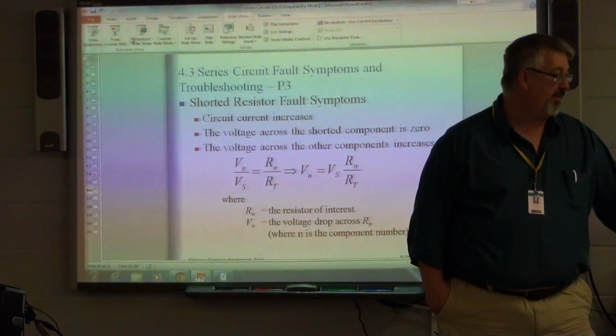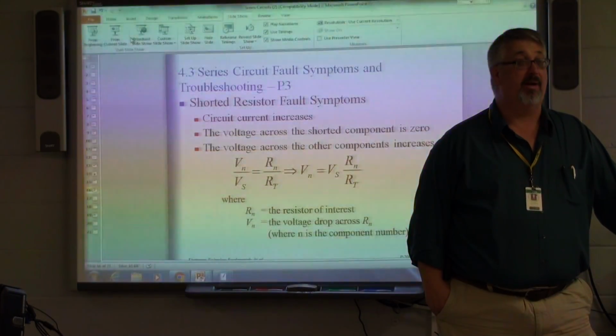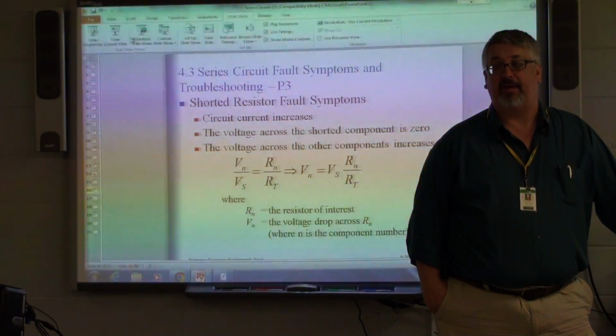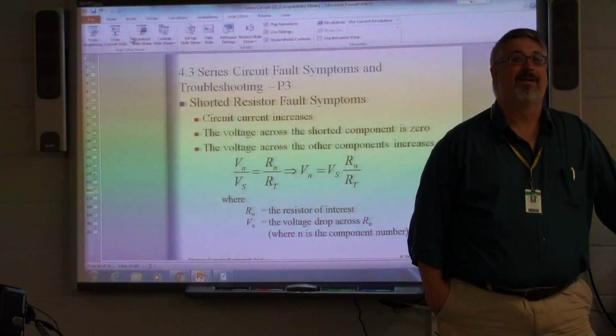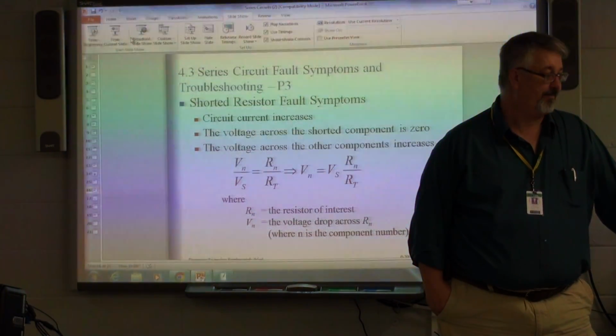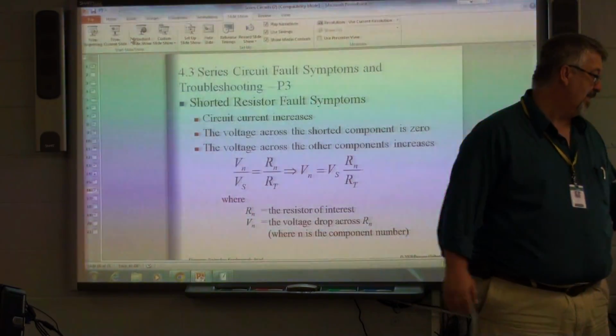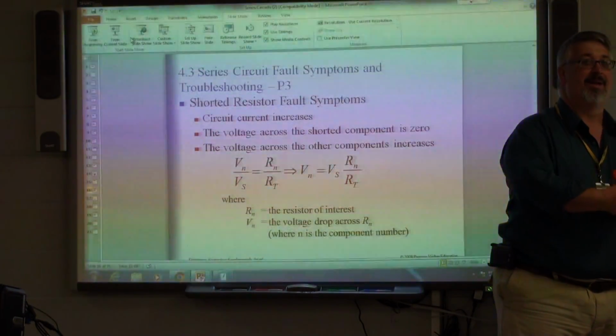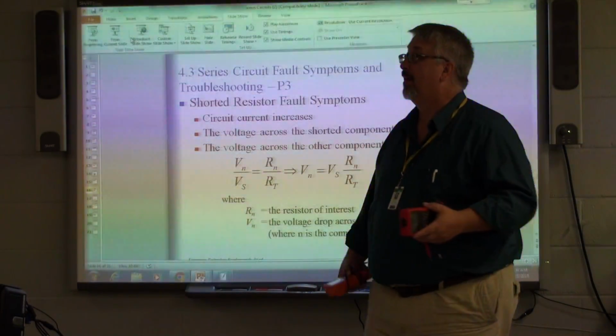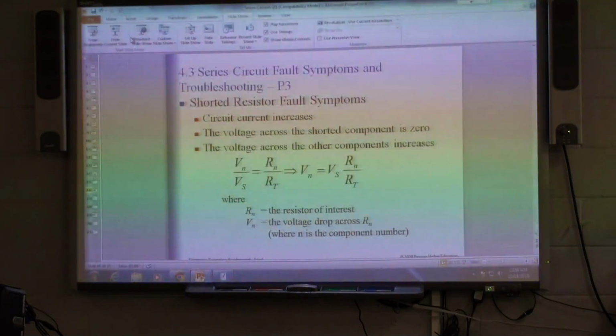So we'll test tomorrow, but there's more to come. We're going to get into parallel tomorrow. Drink your coffee, wear your thinking hats tomorrow. We'll test first thing in the morning. Parallel is not that difficult. Series is not that difficult. In a series circuit, your current stays the same. Voltage drops. In parallel, your voltage stays the same, but your current drops. When they go together, parallel and series, that makes my head explode.